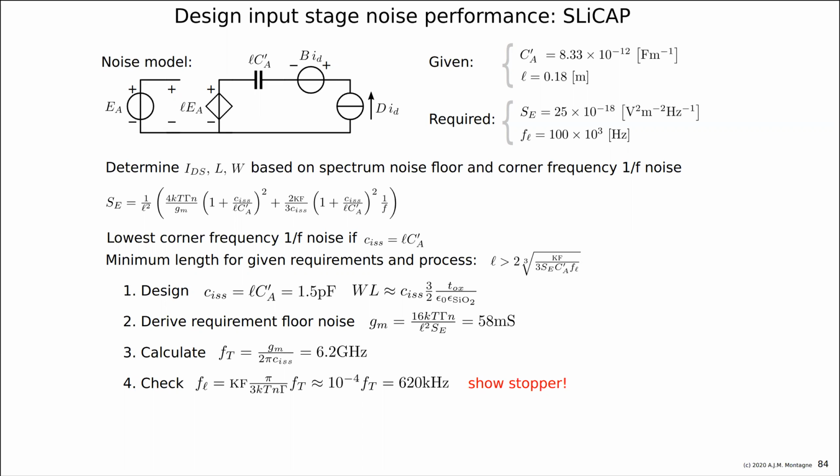Okay. Well, basically, we did the best we could in this process. That's what we did. This is what we have. Changing the topology doesn't help, we cannot use a common drain stage or a common gate stage because we know that the noise sources are equal. So because they are non-energetic feedback stages, that's not going to help us.